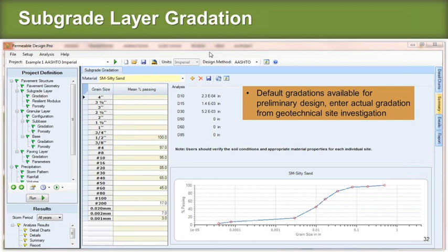And the other is it has good infiltration capacity. So water will get into that subgrade, this is why you see tons of permeable pavements along rivers and lakes. And I'm near Lake Ontario, so there's what used to be Lake Iroquois around the area, and there's lots of sand in those areas. You go to Nags Head, you go to the coast of Maine, you go to the coast of Oregon, lots of great places for permeable pavements that have sandy subgrades. Advantages are, again, it could be thinner because it's got better strength capabilities, and it's also got good infiltration capacity.